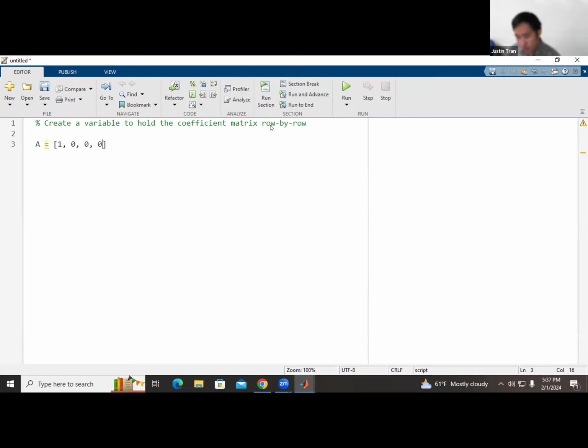To go to the next row, you need to add a semicolon. Then one thing that I like to do, this is optional, you can do it all in one line, is add 3 periods here, just so you can go to the next line and it visually looks like a matrix. All right, so the next thing we're going to do is input the next row. So we're going to do minus 500, 850. Remember, we're separating everything with a comma. Minus 100 and minus 250.